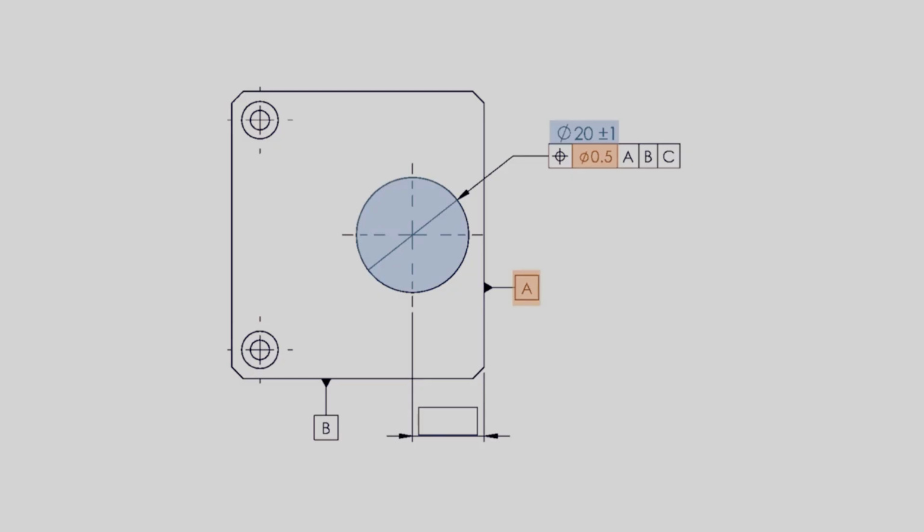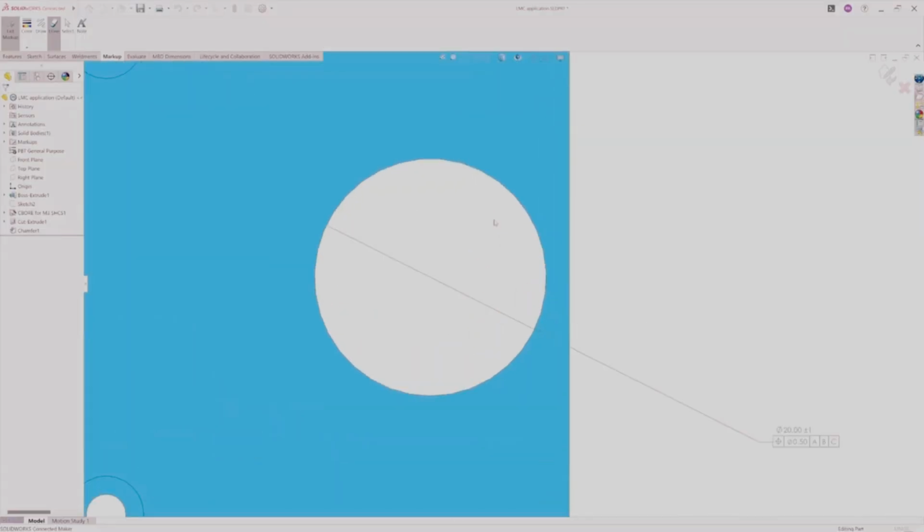This face is datum A. So the wall thickness is very thin. And let's say we need to ensure that it doesn't go below 2 mm. If the hole size increased to its maximum, let's say 21 mm at LMC, even with the maximum position deviation 0.5 mm. So to ensure this, we can specify a basic dimension from datum A, which would be 2 mm,